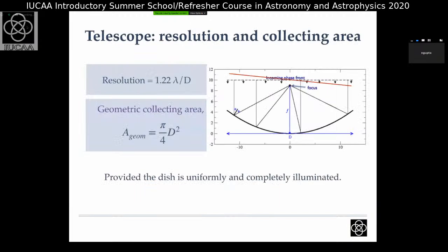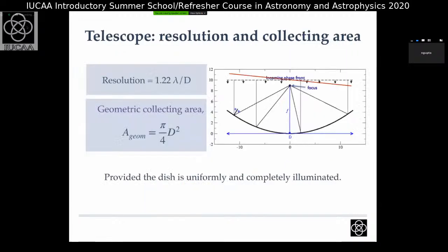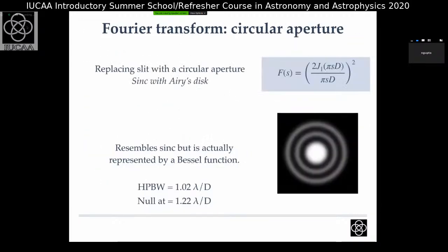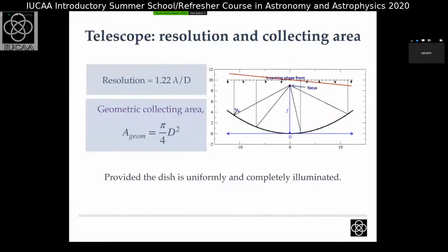Have these big side lobes, right? I want my response to come out nicely, and the side lobes, I know that they cannot go to 0 because my aperture will always be finite, but they should be as small as possible. So what I can do is take a box function or a circular aperture, but multiply it by a certain grading function, which means I can taper its edges, and that would give rise to a Fourier transform which is much smoother in the other domain, right?